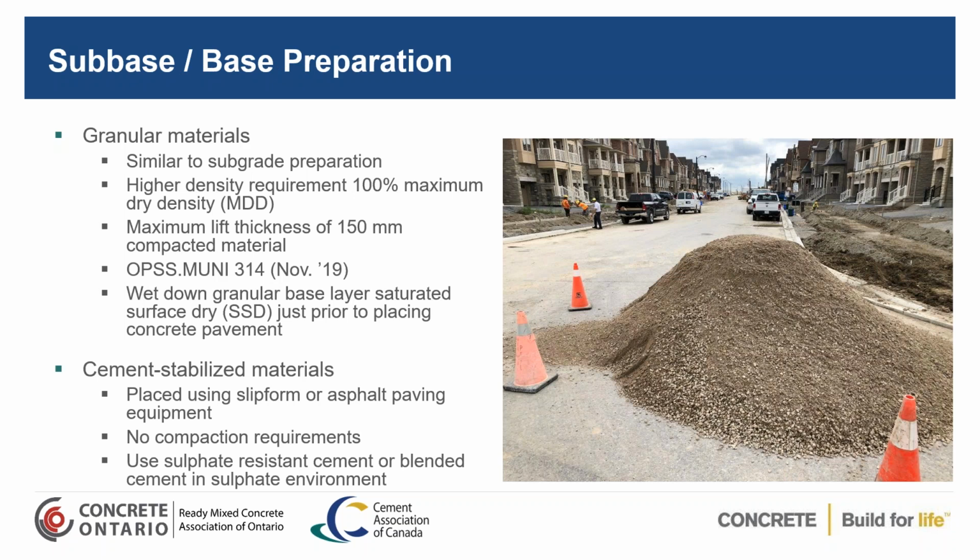Now, the next thing that you're looking at is your granular material that you place on top of it. And as I mentioned earlier, when you're on a 400 type series highway in Ontario that has higher traffic levels, you may have actually granular base and subbase both. In your lower volume traffic areas such as municipalities, local roads, things like that, you may only have a granular base layer to deal with.